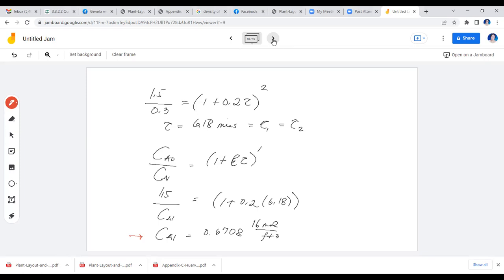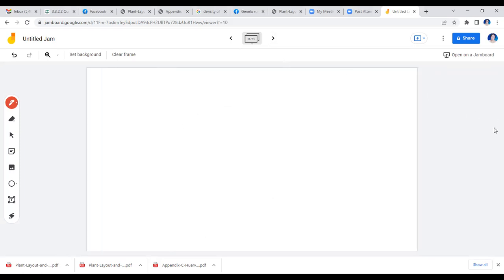So if you're going to write the equation for that, since you have a first order equation, so for n equal to 1, for the two systems inside CSTR1 and CSTR2, you have dCA/dt equal to kCA. So this is your more generic formula. And from in here, from what we have discussed already in kinetics, you will have C sub A over CaO equal to e raised to negative kT.